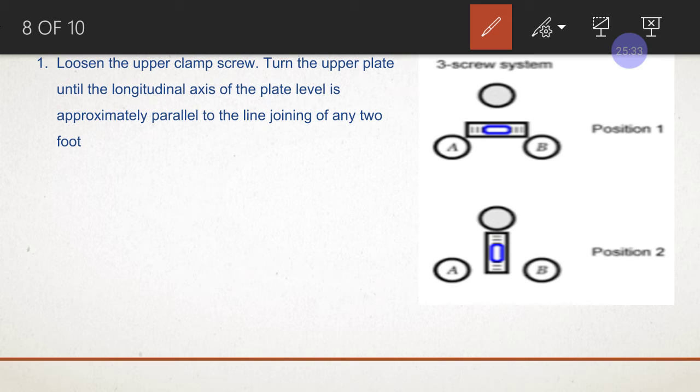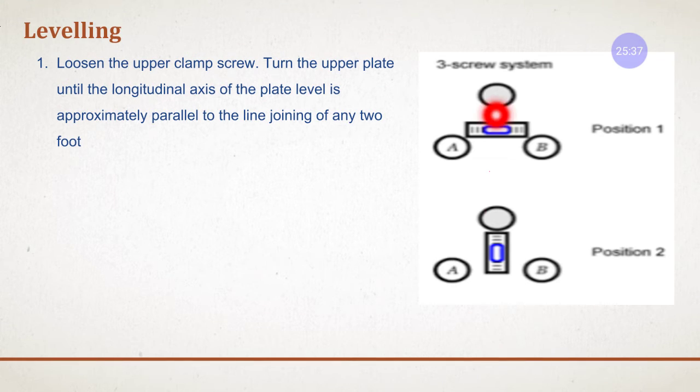Right? Can you see this? The bubble, this bubble is at the center now. Once you turn clockwise, both these screws are turned clockwise, then what you are going to do is turn the foot screws either clockwise or anti-clockwise simultaneously till your bubble comes to the center of the bubble tube,